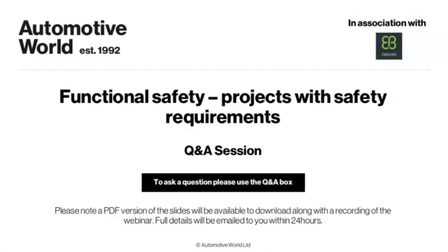Basically, for a safety element out of context, you need to take certain assumptions on the system and on the environment, and you need to document them. This is something which goes into the safety manual. Then, based on these assumptions, you derive requirements, and based on these safety requirements, you implement your system or your software.